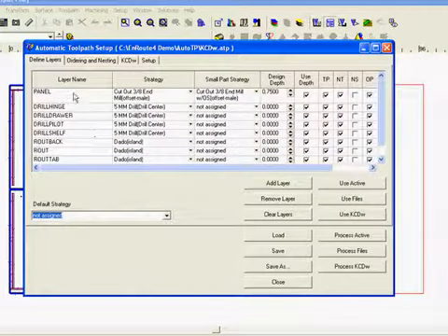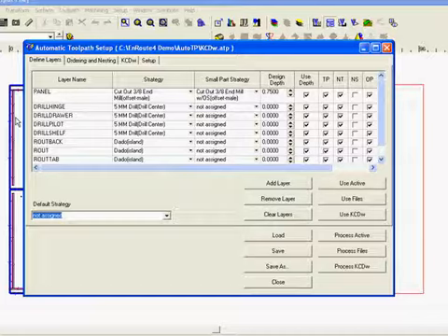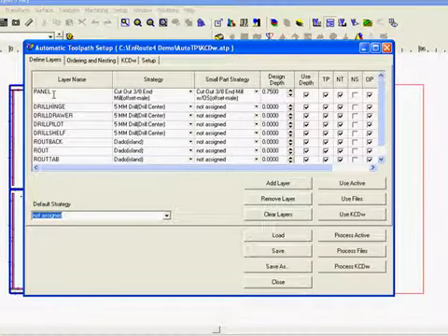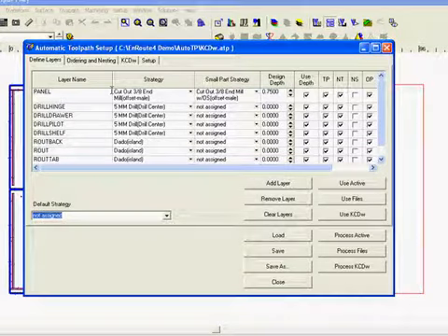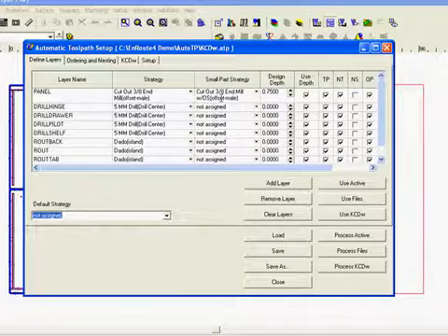You can see we have a bunch of layer names, and when you're doing this auto toolpathing, each part you create is in an individual DXF file. Each geometry within the part is in a different layer name. So what Enroute does is read the layer names, apply a pre-existing strategy to each layer name, and it allows you to have a second strategy for small parts as defined by a tolerance. So anything over a specific tolerance is considered big, anything below it is considered small.